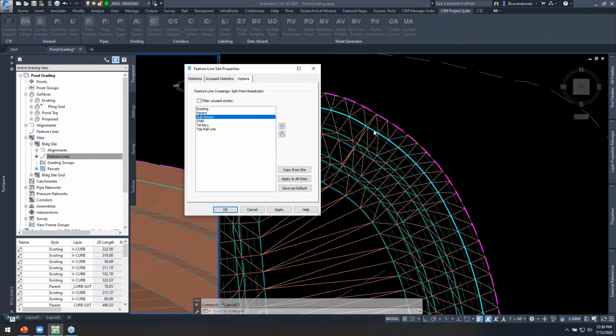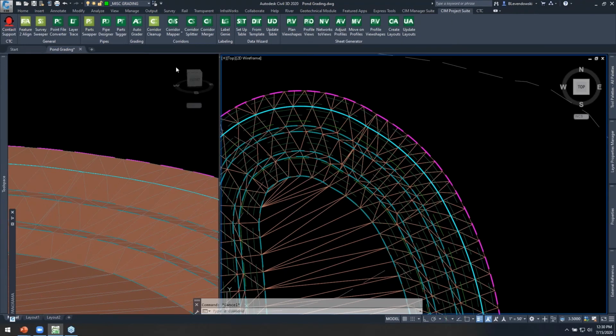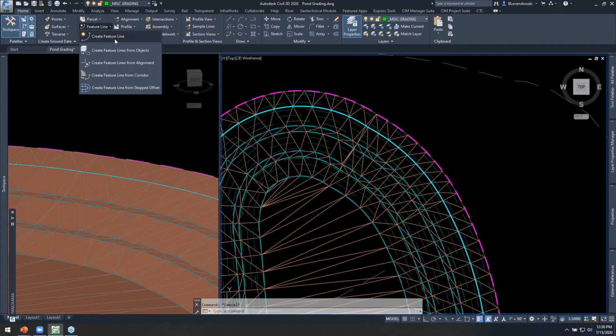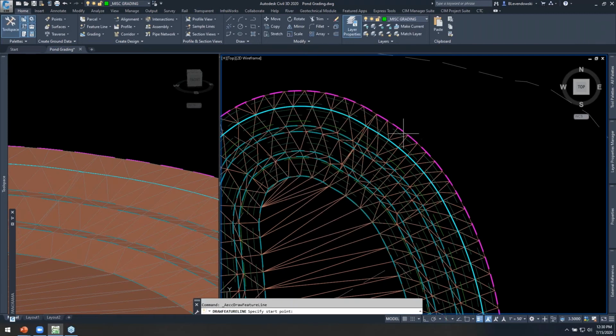And what I want to do is draw a feature line that's going to stay dependent on the parent, meaning the pond baseline, but it will control the elevations of the pond berm. So the magenta line out here is the pond berm, and it has a style of child. Okay. So here's how it works. It's pretty simple, in fact. Some of you guys have maybe used this trick in other workflows. We're going to grab subparent style. I'm going to hit OK.